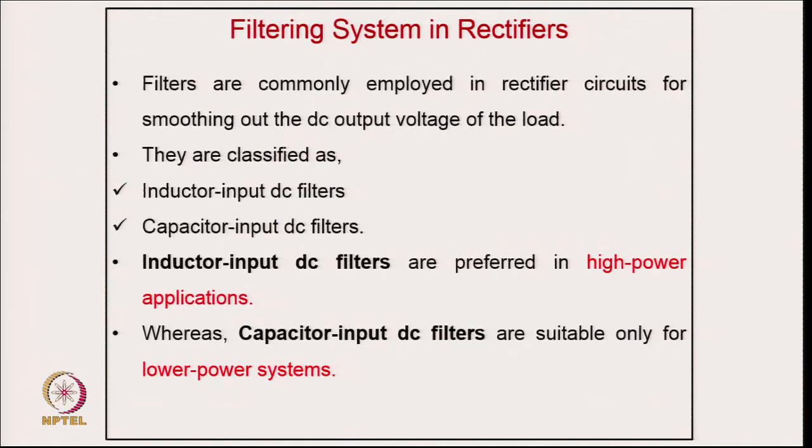Of course, in the single phase case, filters are commonly applied in rectifier circuits for smoothing out the DC output voltage of the load, but this certainly affects the power quality on the input side. So they are classified as inductor input filter and capacitive input filter. The inductor input filter is preferred in high power, whereas the capacitive input filter is suitable for low power applications.